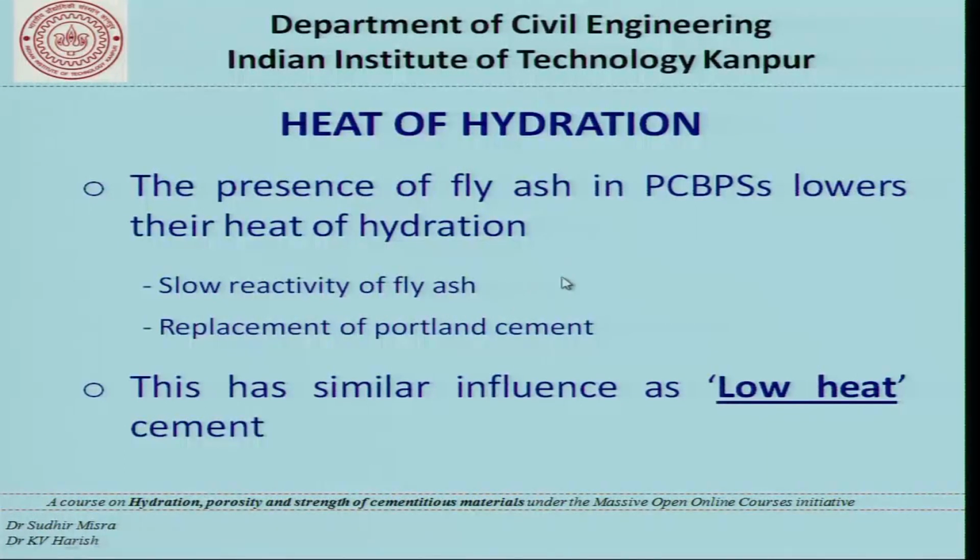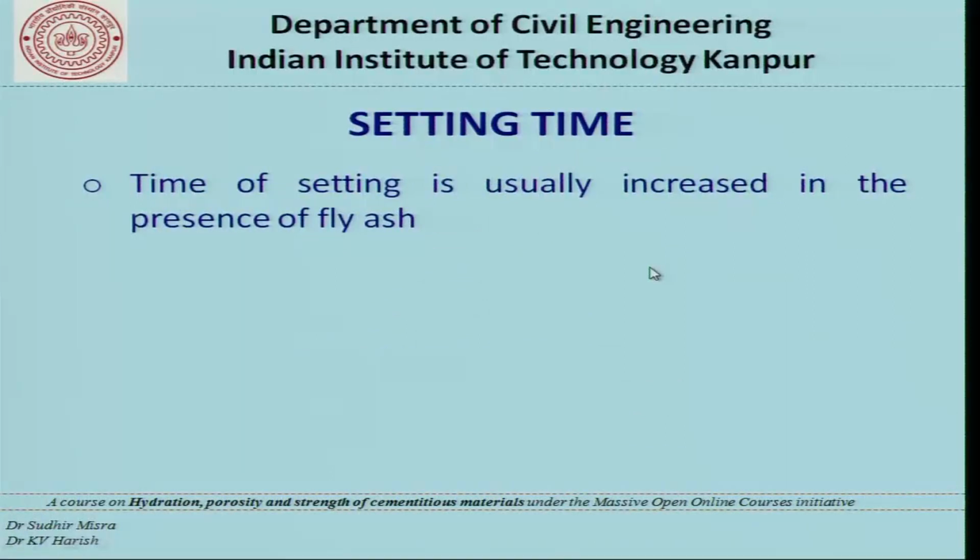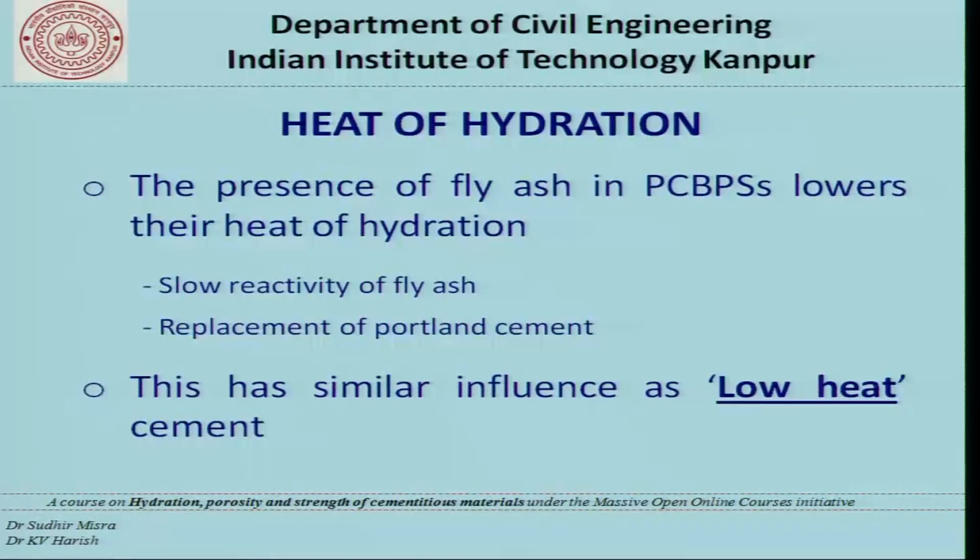This is also similar to what we have discussed in setting time, where the portion of cement for the fly ash mixtures is usually lower, and hence the properties are beneficial when you use fly ash. And this lowering of the heat of hydration for the fly ash mixtures helps to use such mixtures for low heat applications.